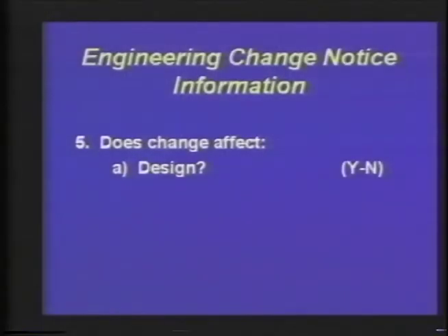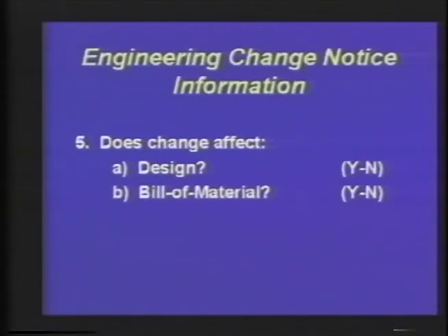Now, step 5 addresses the questions of the design feature of the equipment, and that would be more operational, speeds and feeds and temperature or any other application relative to changing the asset. 5B, I'm using the term bill of material, and I've identified that earlier, are the spare parts for that asset that are going to be used by maintenance to maintain the equipment.